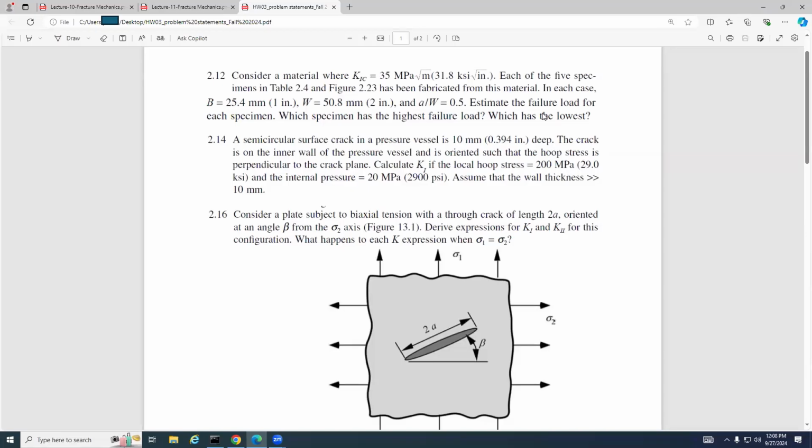Student: I know there's an equation for each f(A/W) for each specimen, but there's also the graph. Could you just use the graph instead of plugging all the numbers into the equation? Instructor: When you get values from the graph, it's not very accurate. I would suggest using the equations. Equations are analytical. With the graph, sometimes we are human, so different people select slightly different locations. Understand? Use the equations.